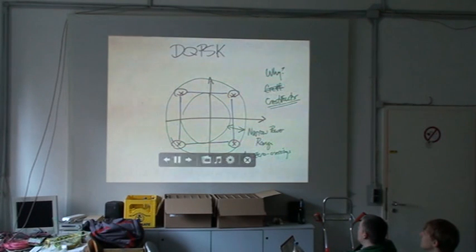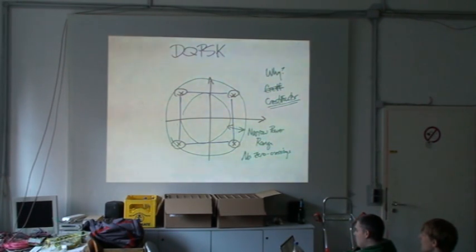You're like, why in the hell would you do that? You've built a system that's more complicated than BPSK, but it doesn't transfer any more information than BPSK. Why would you do that? The answer is something called crest factor, and this comes into play again as we keep moving down this path.